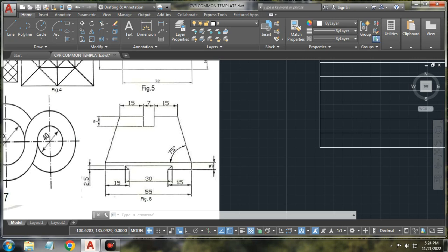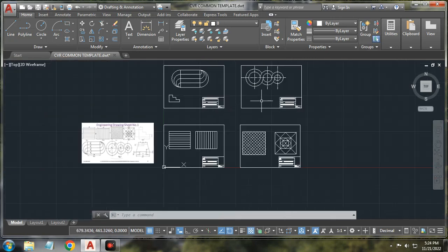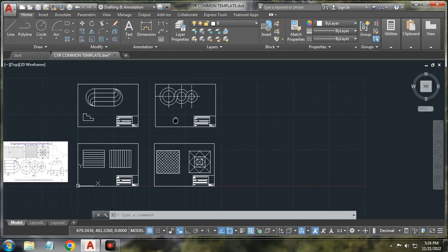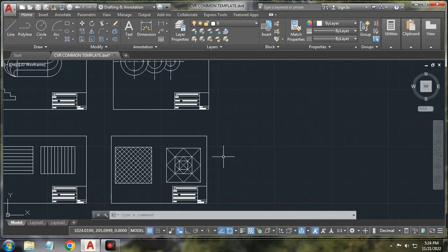angle is 75 degrees. External angles generally we take in the counterclockwise direction as positive, so you have to consider the external angle method. In the external angle, 180 minus 75 comes as 105. So whenever you are typing, you have to take the angle as 105. Okay, I hope everyone understood this one. So I am starting. Okay, so I'll be creating one more new template for drawing it.